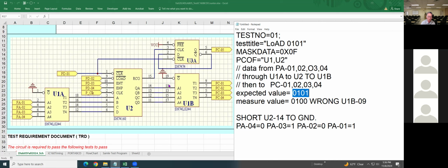In general, you say input is right, output wrong, right? Right. That can be one. However, in here, that's not enough. What about checking pin 19 to make sure it's grounded? Exactly.